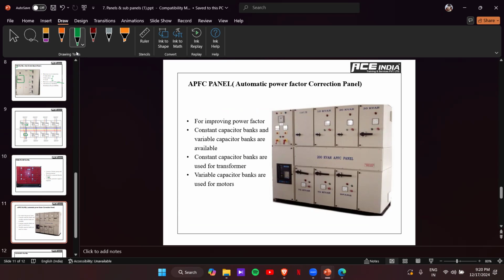When you turn on a motor in the house, you can see that our light will blink for a second. That is because motors are a kind of inductive load. Whenever we turn on the motor or pump, it will take more starting current. In a commercial space or building, a lot of inductive loads, pumps and motors, will be used. Just imagine what will happen if you turn those on. It will affect other systems.